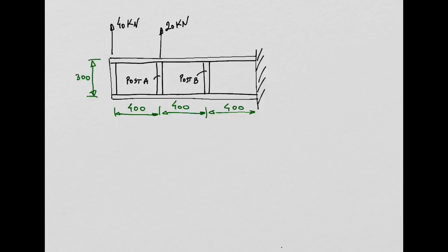Okay, good. Now, a Wagner beam spar, equally spaced posts. Web thickness is constant, so the thickness is constant and equal to 1 millimeter. So you can see very thin, right? Very thin webs. And then they are saying here, the loading has resulted in a fully developed diagonal tension field throughout the spar. Okay?